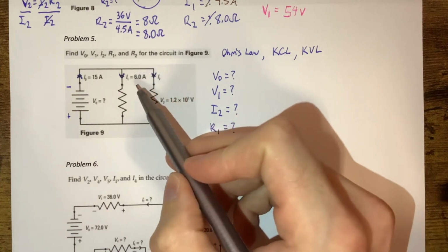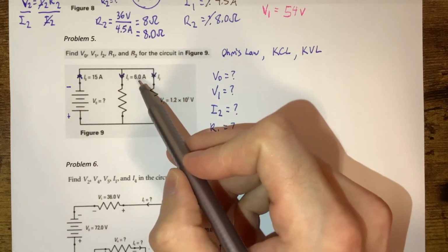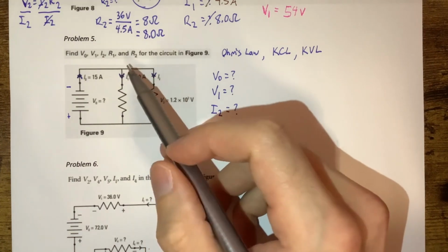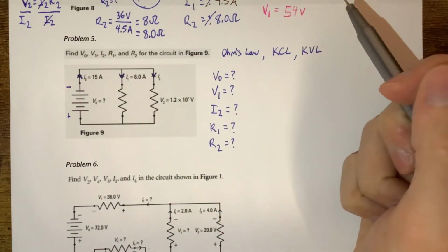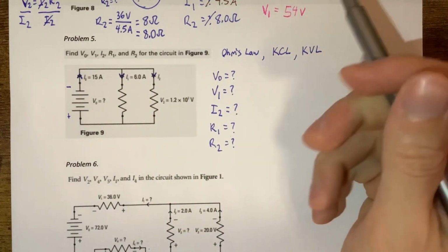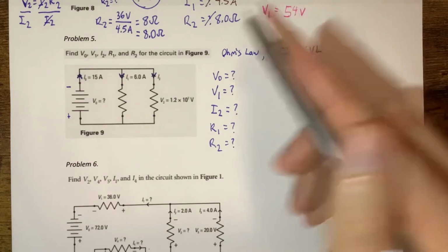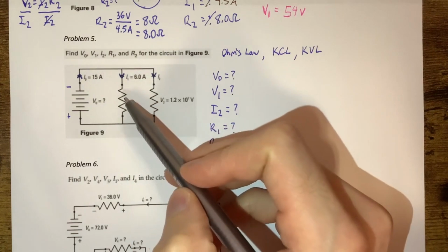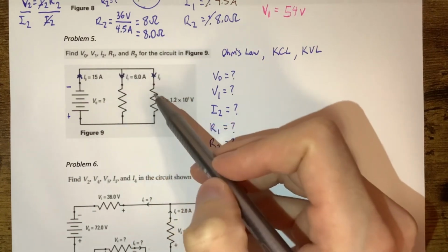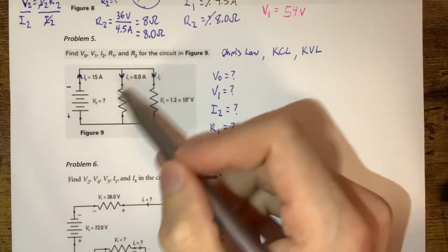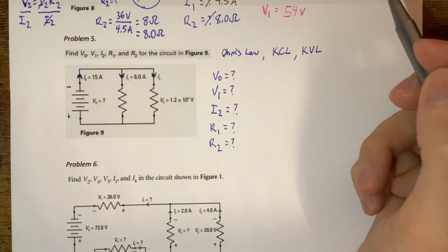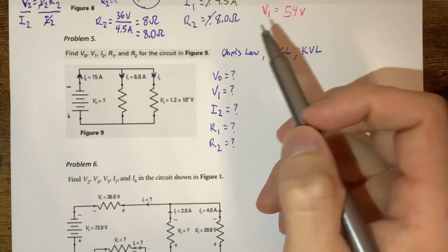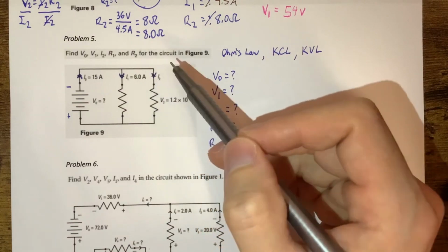And we already see that we split here, and this is going to be 6 amps. So at I1, 6 amps went down here, and we can't create charge, right? So we can't just create electrons out of the blue. Whatever we start with here for our current, if we split 6 down this path, the remaining is going to split down here, okay? And we see that with a parallel circuit, okay? So current into a junction, think of a fork in the road, is going to equal the current out, okay?